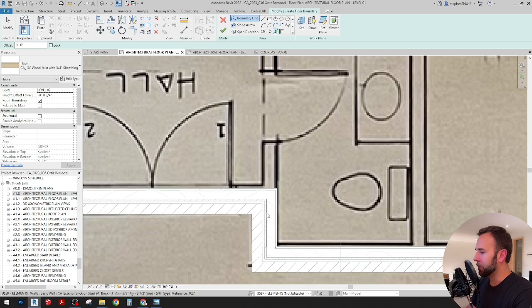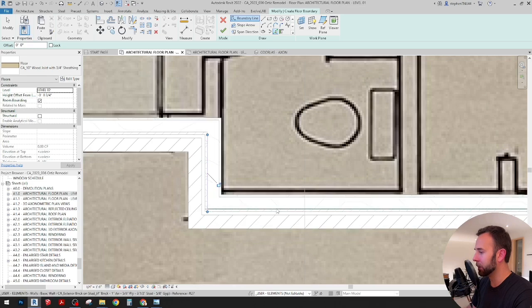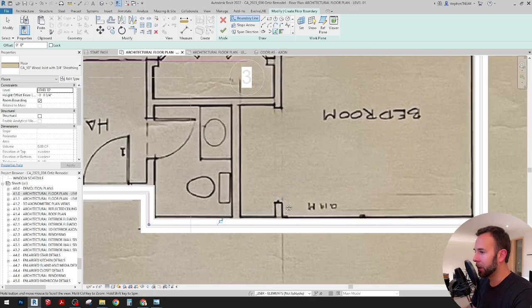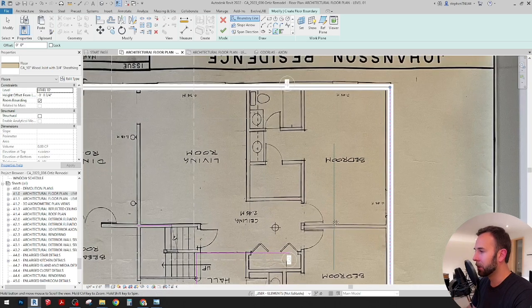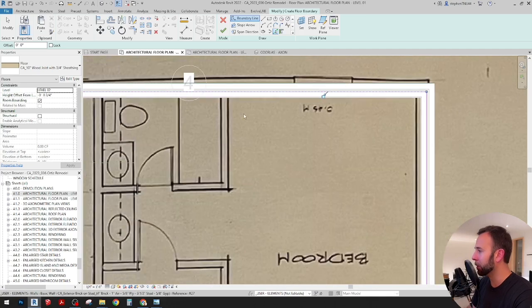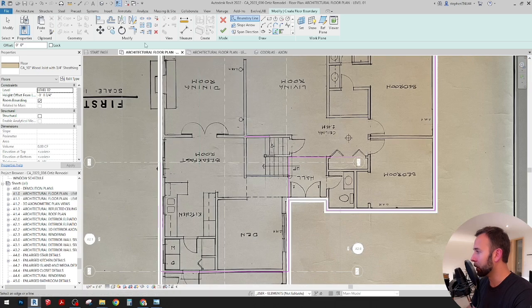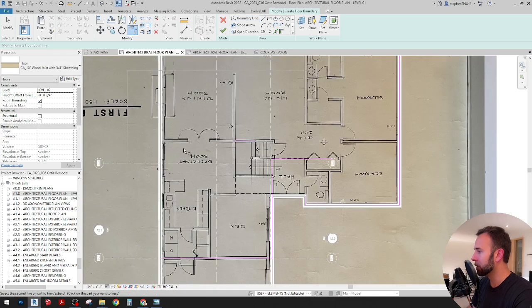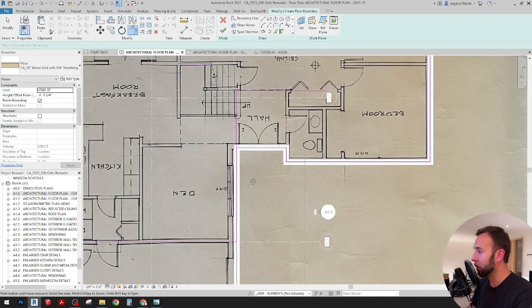And again, the reason why we like to do the surveys is because, as you can even see, one was hand done. It looks like a long time ago. And we always find that dimensions of as-built are different from plans, even permitted plans, and what's built and on site. So it's important to always do your own surveys and go off your own dimensions.